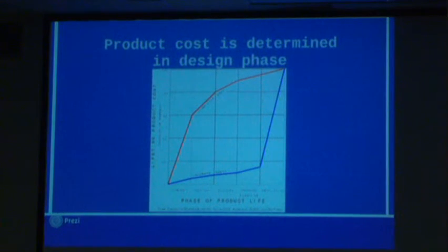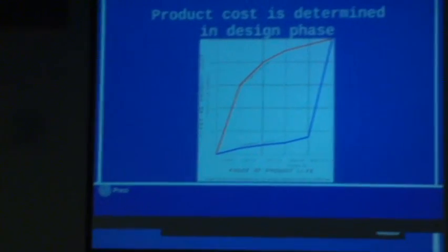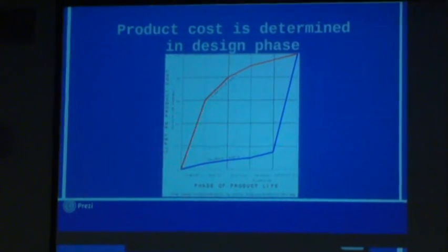If you look at the committed cost, at the end of the conceptual design phase, you're in at 60% of your committed cost. So what that means is the design that you had can only be made in such a way that you've spent this money. Whereas if you include your manufacturing engineers up front, you can get that 60% to be as small as it can be. Okay? So the very concept of your design will dictate most of the cost of it. It's not the production method as much as it is the design. Okay? So if you get into an existing part and you say we need to make this cheaper, and you start thinking about how could we manufacture the same part in a different way, it's a lot more difficult than designing it appropriately to begin with.